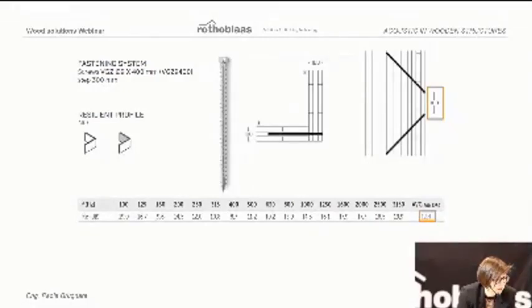It is an interesting result, and it is due to the fact that we don't have the contribution of the head of the screw, because the head brings the elements to a closer contact. And of course, if we have this closer contact, it is easier for the vibration to pass from one element to another.